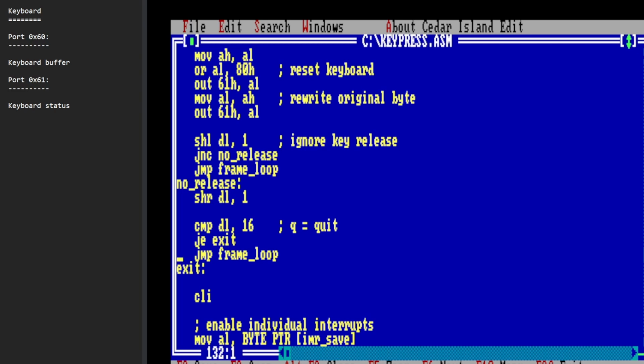Now it's actually up to you what you do with the information that you get from the keyboard. So there's not a separate scan code for lower and uppercase A, for example. So you actually need to keep track of whether or not the shift key was being held down when the A key was tapped in order to know whether it's lower or uppercase. And so there's a little bit of work involved in dealing with the keyboard, but for what we're doing, it's pretty straightforward. At any rate, this is all we need to do here.